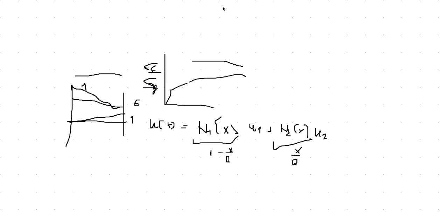Then I can take sigma of x. An easy way would be to call it some function, M of x, times beta, where beta is the stress parameter, and the simplest choice for M is simply 1. Now I can define my interpolation. I have to have a hybrid stress approach.